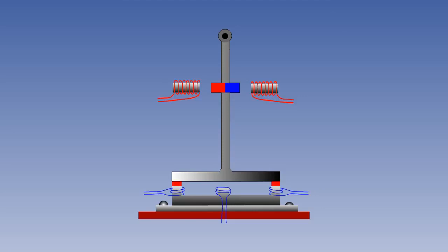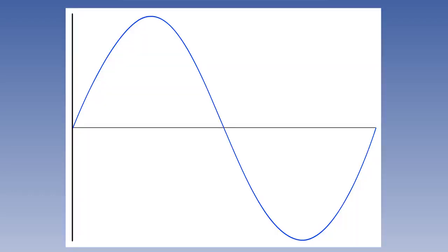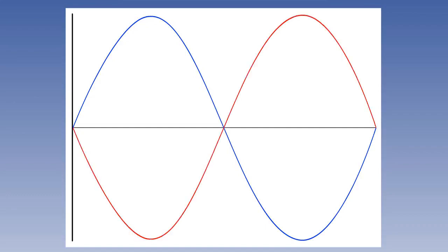The amount of induction in the secondary legs is affected by the gap between the E-bar and the I-bar. The I-bar is attached to a rigid pendulum and hangs vertically when there is no lateral acceleration. If the gap is the same, then the amplitude of the voltage induced at the two ends will be identical. But the polarity will be opposite, because when one end is a north pole, the other is a south pole, and vice versa. The positives and negatives cancel each other out, and we get a resultant of 0.